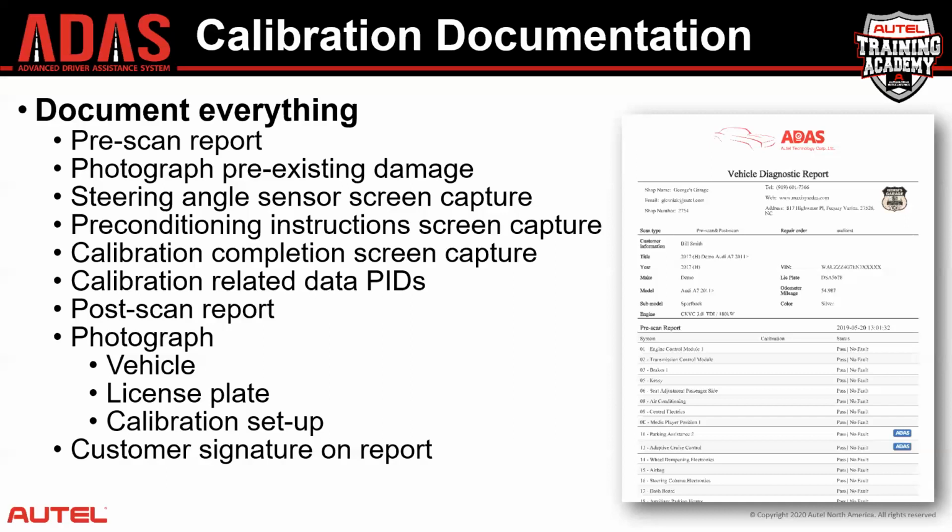And then the post-scan report. This is after you've calibrated and test driven the vehicle. You got all that documented. Bring the vehicle back after you're satisfied that the system that you calibrated is functioning properly. Then do a post-scan report that will show the state the vehicle was in when you're delivering it back to either your customer, a consumer, or to the other shop that you're contracting with.